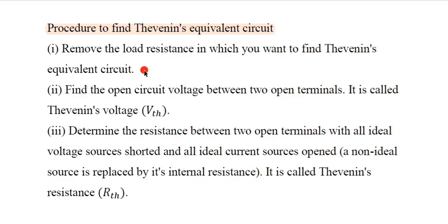That is the first step. I will illustrate with a numerical example also. When you remove the load resistor, keep the terminals as open terminals.